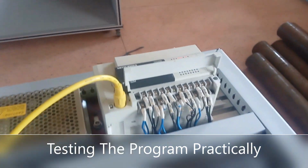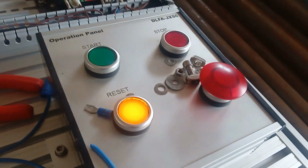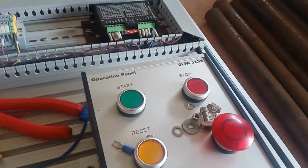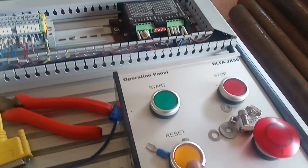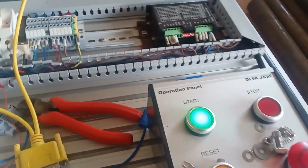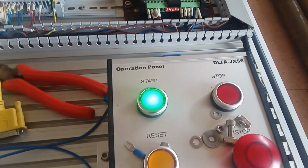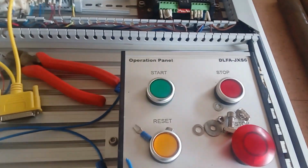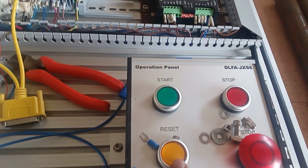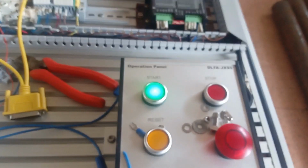Once we've turned the PLC to run mode, we can see that the yellow light is blinking according to our program, and when we press the yellow light, we can see our start button blinking. We need to make our start button blink when all the processes have reset to their initial position.